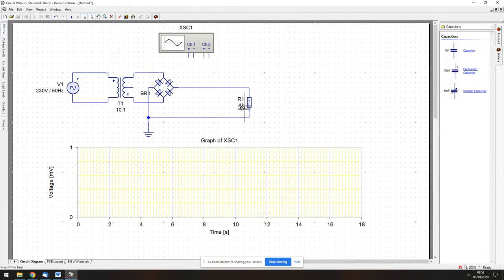I'm going to pick a 100 microfarad capacitor and drop it in. That's all we're going to do. I could have kept that, so I'll put these slightly out of the way, and then I can build the rest of the circuit, because we're always really going to trace with the DC coming in now. And we're going to again look at what that output trace looks like.